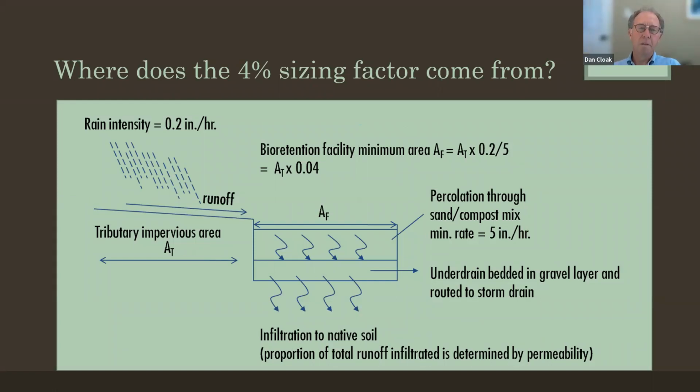Another look, yeah. And then a question from the chat also: if the water table saturation zone rises into the gravel, does it increase water getting into the storm drain that would have otherwise risen to just below grade or stayed in the ground? Yeah, maybe. This distance is 18 inches, so that's pretty high groundwater. Below ground level, we're supposed to have a 6-inch reservoir, so really the depth that you need is 2 feet.